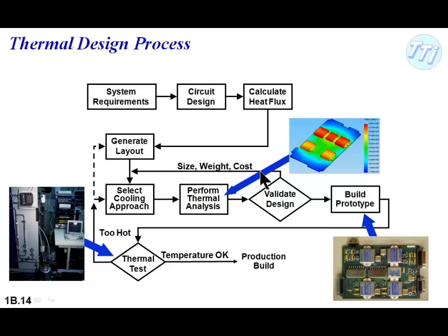So again, just an overview. What are the general steps to a thermal design process? You might be involved in just one portion of this, but this is the general. In an ideal world, if thermal design is important to a particular product and it's adequately funded and provided for, you start off with deciding what are the system requirements. This gets left out so frequently. People don't understand necessarily what temperature they want to run at, what are the environmental conditions. Is it going to be in the desert? Is it just going to be inside a temperature controlled building?